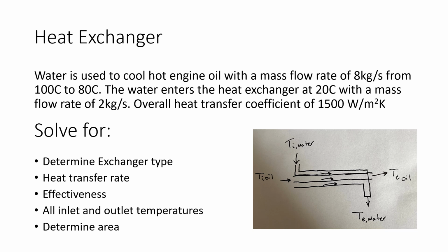All right, we'll get right into the problem here. In this heat exchanger, water is used to cool hot engine oil with a mass flow rate of 8 kilograms per second from 100 degrees Celsius to 80 degrees Celsius. The water is entering the heat exchanger at 20 degrees Celsius with a mass flow rate of 2 kilograms per second. And this has an overall heat transfer coefficient of 1500 watts per meter squared Kelvin.